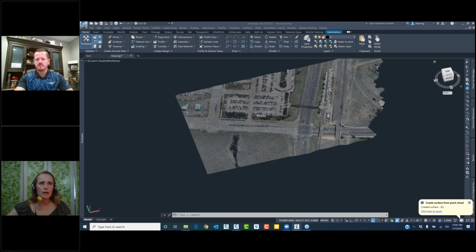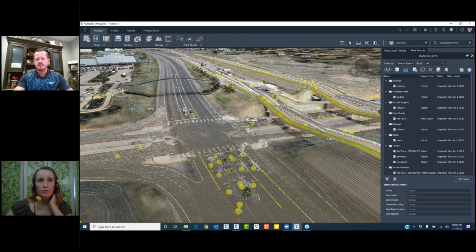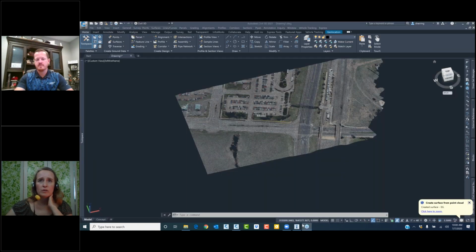D_Lindsay_BIM is saying the Recap files can be linked into Revit very easily. The main thing with a Recap file is setting up the origin point to match up with the origin point of your Revit file, the X, Y, and Z. I wish there was a little more control in Revit over the Recap file like there is in AutoCAD, but Recap files can definitely be utilized in Revit. So thank you for adding that.